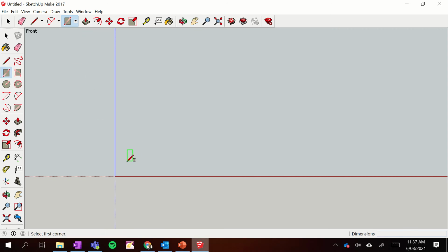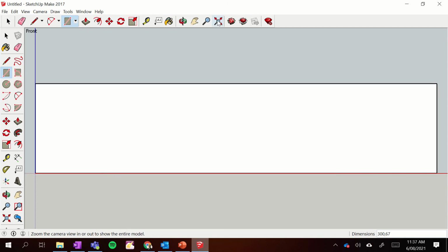And you'll see that if I go down here, right at the corner of my pen, my pen does say the origin, and if I click there with my left mouse button, and you may have heard me click then, I can start to draw. Now what you will notice is over here, the dimensions are there, and if I start typing, I can actually start typing the dimensions that I want. So I want 300, if you have a look down there, you can see this is what I'm typing, 300 by 67, and I end up with a piece like that, and whoa, it's really tiny. But if I click this button up here, it then makes it so that I can see it.